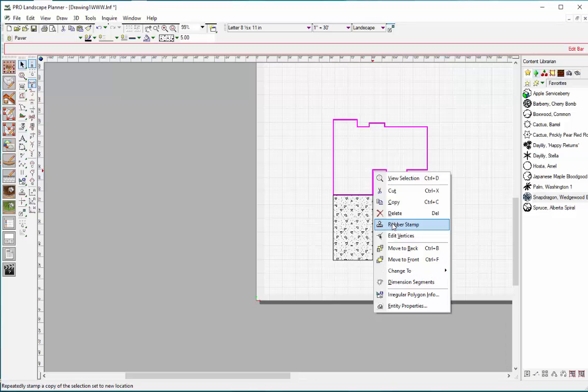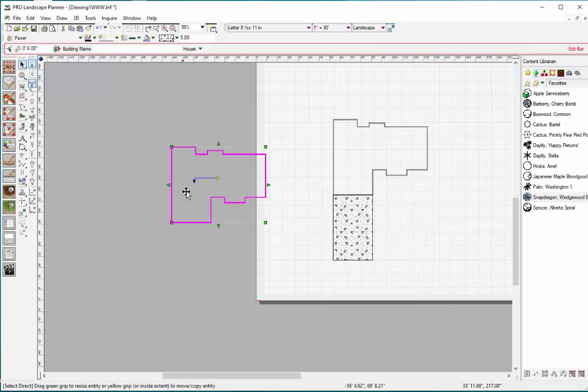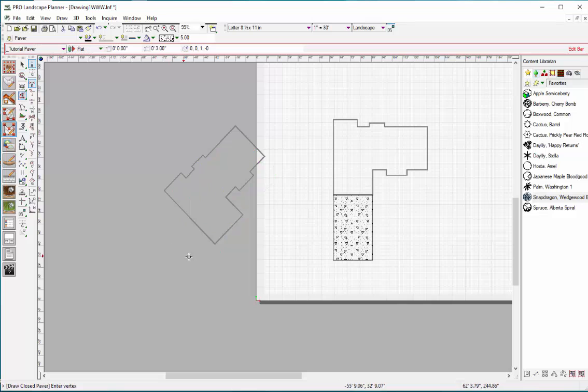Now, it doesn't really matter when you use this normal lock key if your foundation is set even with the grid. So what I'm going to do here is rubber stamp it, pull it out here, and then rotate it, and use that same technique. Okay, so I'll use my close paver, I'll click here, come over to here, hit the L key on the keyboard, and that gives me a perfect 90-degree angle based on that first line that I drew there.